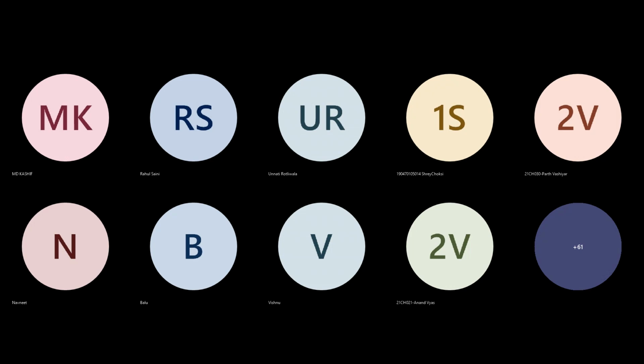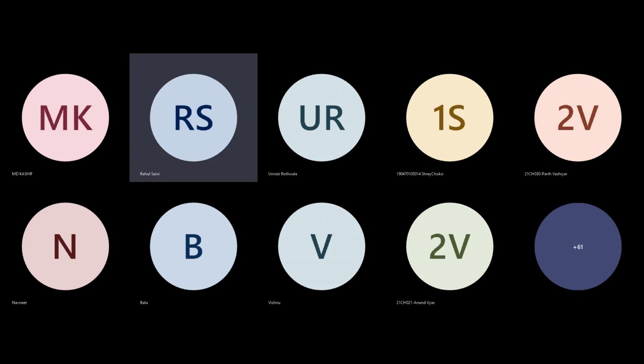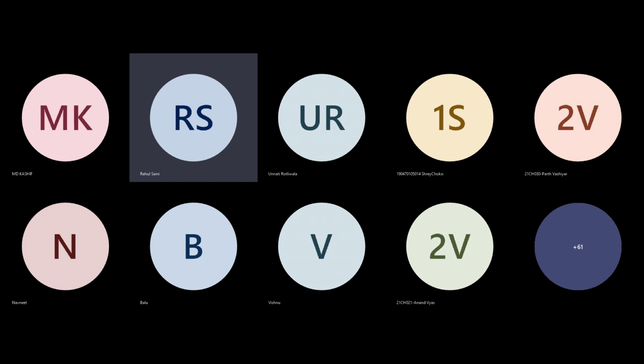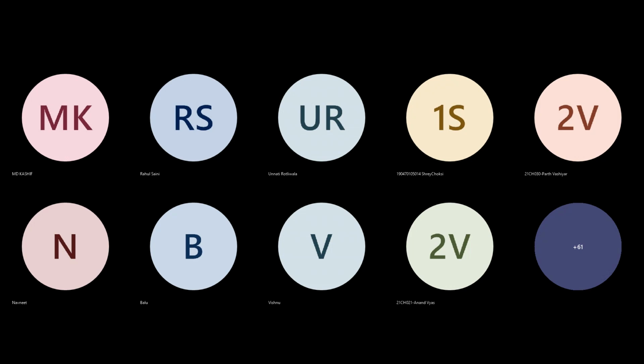So how do we calculate NPSH available? Based on the pressure drop we will be getting from the pipeline through which we are drawing the liquid to the pump. NPSH available is basically your suction tank pressure plus the pressure because of the static height of the liquid inside the suction tank, minus the frictional losses in the suction, minus the vapor pressure of the fluid in the suction side.